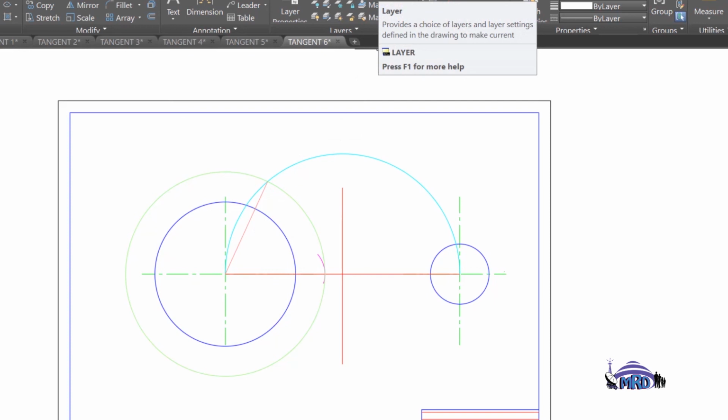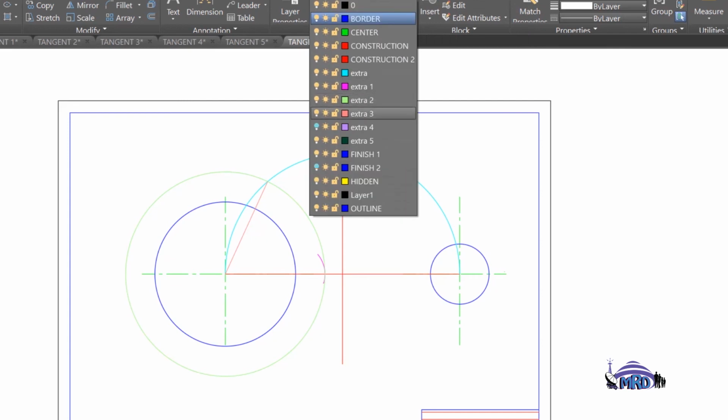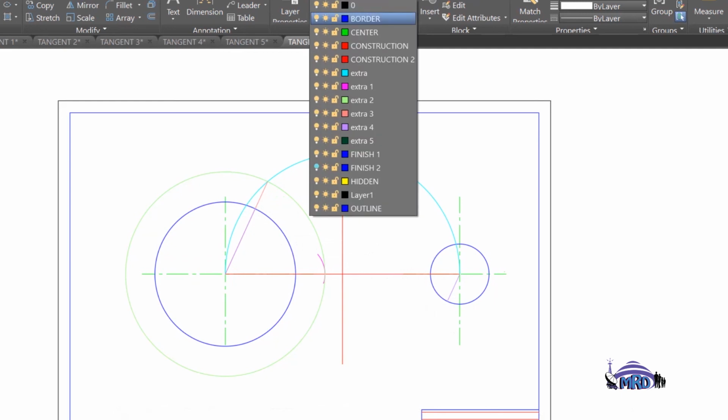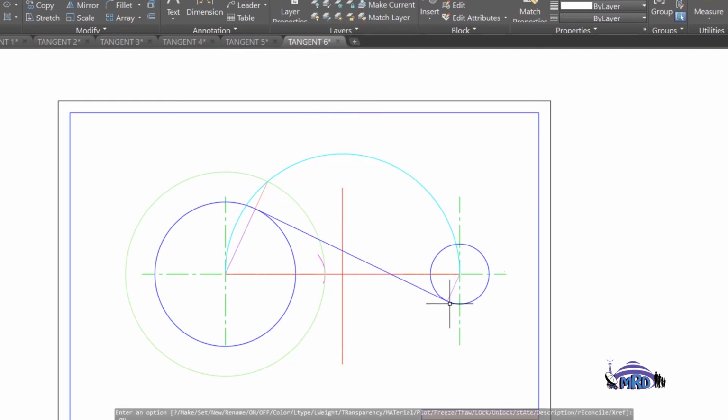and you need to get a line now parallel to this, but that parallel line will fall on the other side. So if I show you that new normal, it is now going down on the opposite side to allow you to get the internal tangent. And just to complete, you connect the points of intersection formed, and this would be an internal tangent to two circles of unequal diameter.